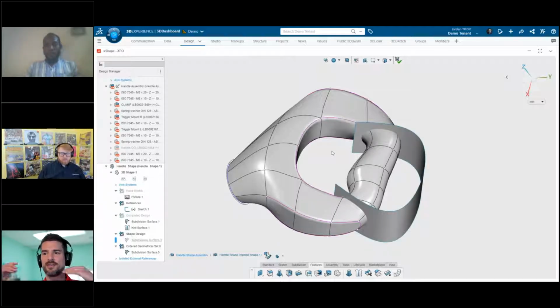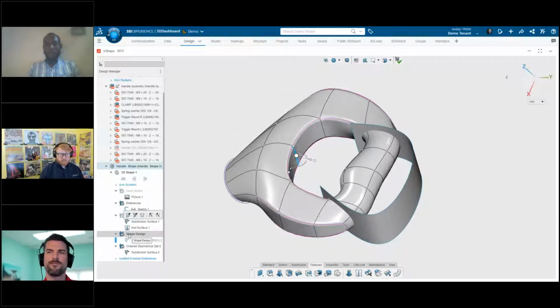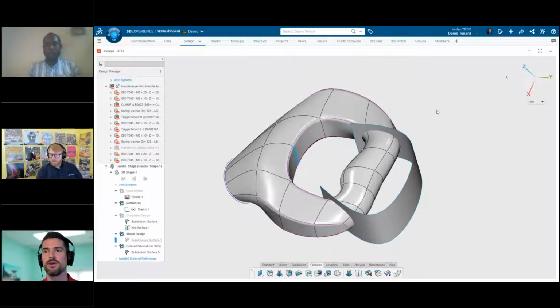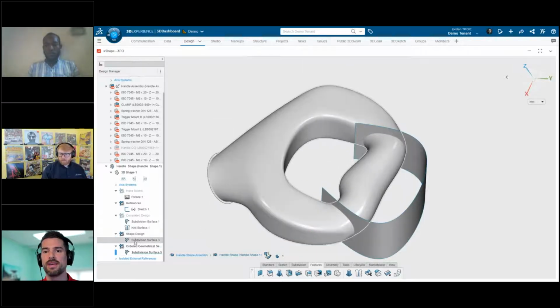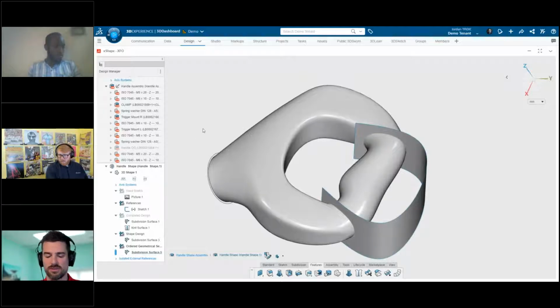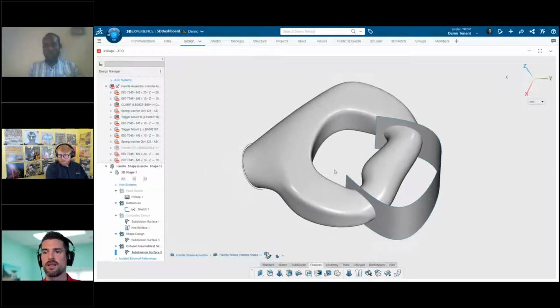And we know that if you did that in SolidWorks, once I edited this original shape, the downstream features would disappear because they're dependent on the upstream features. But by putting these in separate folders called ordered geometrical sets, this is some power that we're borrowing from CATIA. It allows us to make changes upstream while still referencing the downstream features, which is really cool and kind of fascinating, because unless you're in an assembly or something like that, there's no way to do that inside of SolidWorks.